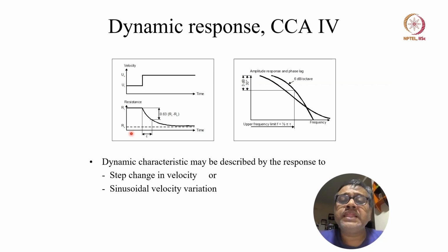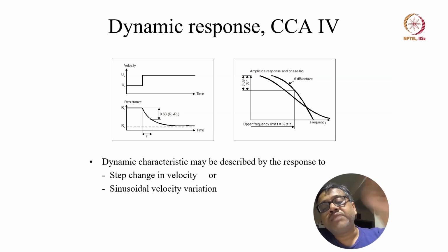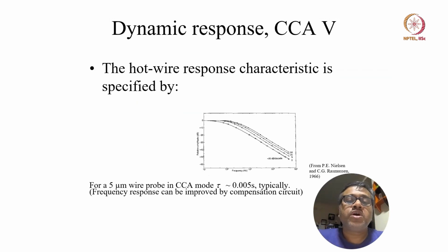So there will be a little bit of a phase lag, and a little bit of a time delay. This is the time delay by which the hot wire catches up with the change in flow velocity. It can be a step change, it could be a sinusoidal change. This is how the response function acts, that means how the hot wire responds to a sudden jump in the velocity. The hot wire response is more a characterization of the same. This is the dynamics.